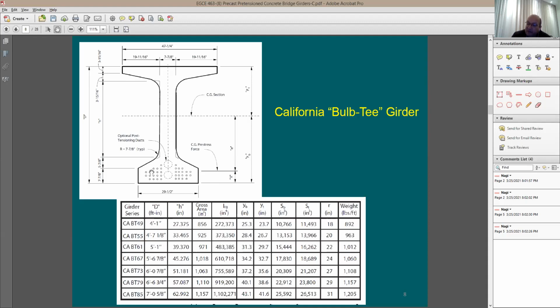After you put it in place, you can add more post-tension to it at the side of the bridge. So it is first a partial pre-stress, and then after you move it there, if you'd like to add more pre-stressing to it, you should be fine. But if the length that you ordered was good enough without this additional post-tension, then you should be fine.